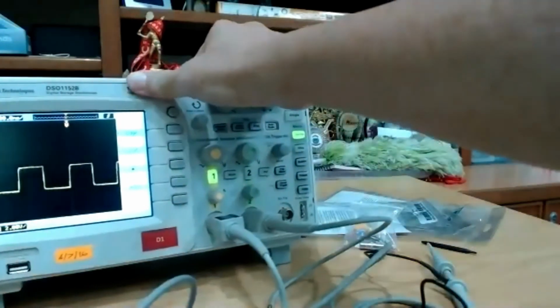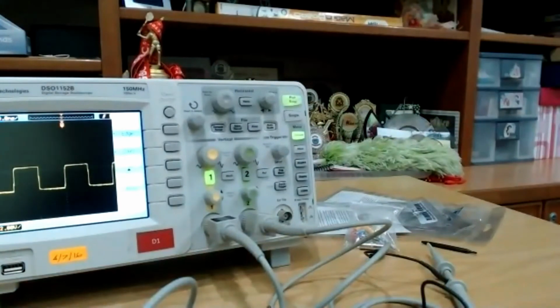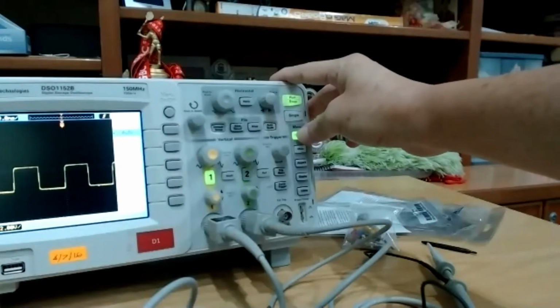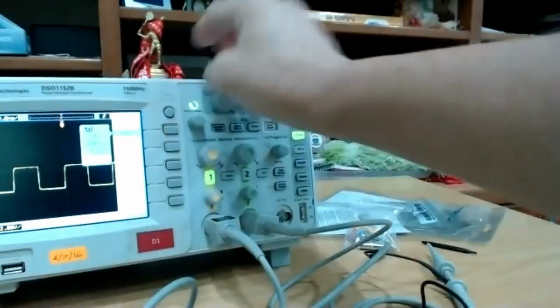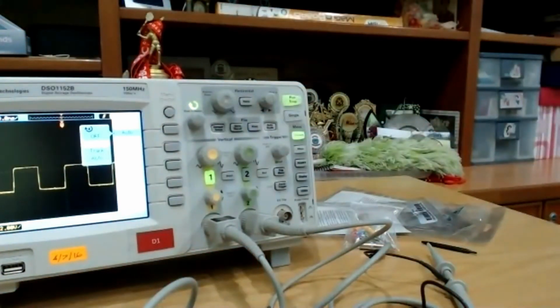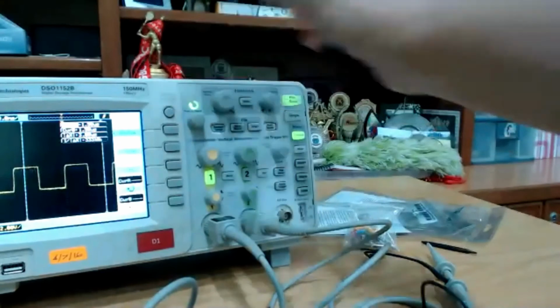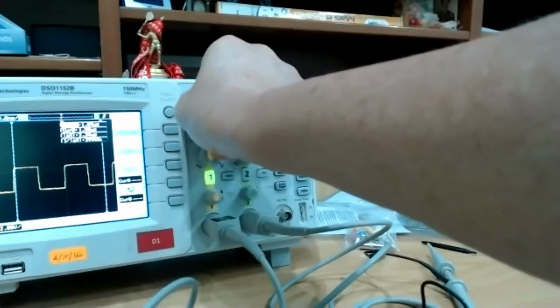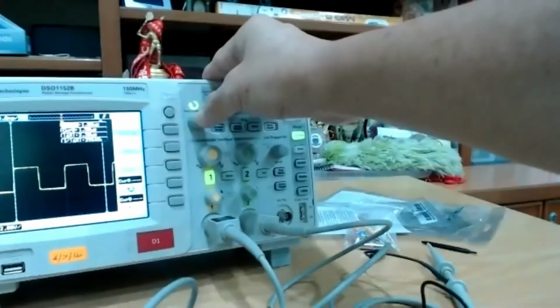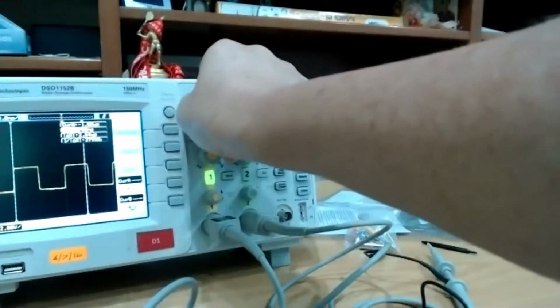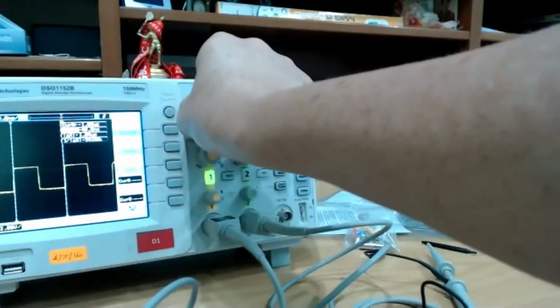I need to explain that you can do measurements on the scope using the cursor. For example, if I put in the cursor, I set it to manual, which means I want to manually change the cursor position according to my own intention. I can change the cursor to measure from position number 1. We call this cursor A. Then I can change the position when I press the button. And this is 1 period.